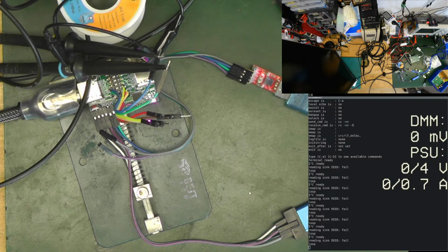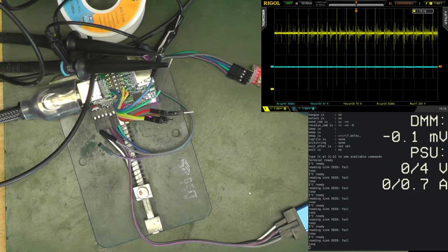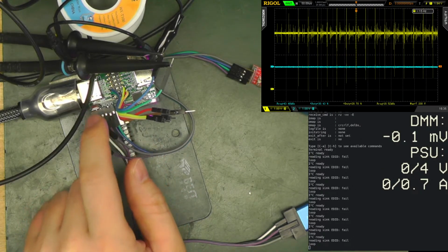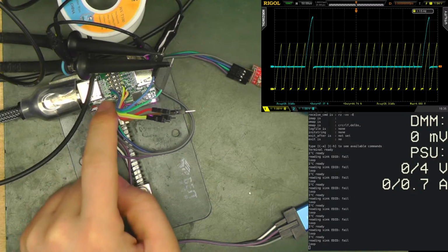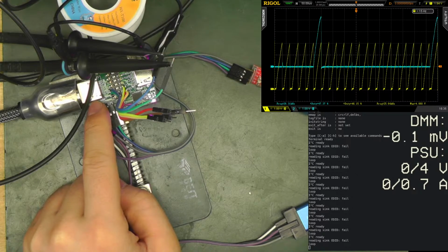I need to switch on the oscilloscope for you. Let me switch it on. Oscilloscope capture. Okay, that works. So let's start a read and see if we can trigger on it. Yes, we can trigger. So we see some I2C data traffic, but it doesn't look very nice because we have weak pull-ups on the sink side.